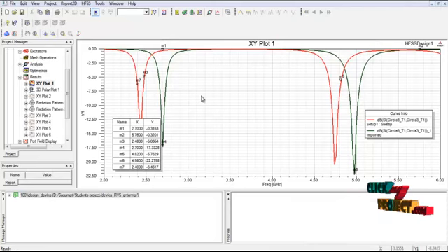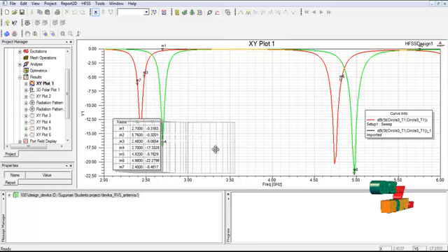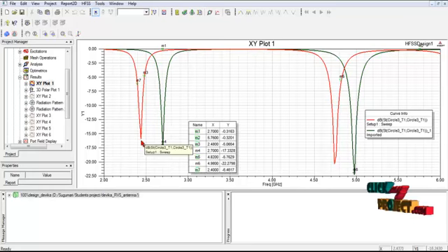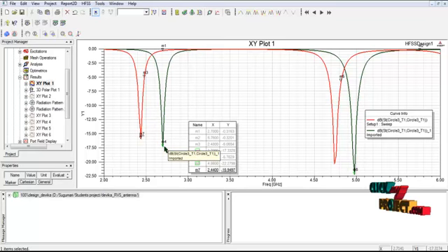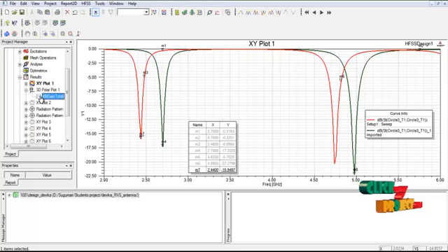yeah, this is the return loss graph. Below minus 10 dB is the working condition of the antenna. For example, this point is indicated at 2.4 GHz, minus 15 dB, and M4 is at 2.7 GHz, minus 17 dB. So like that, this is the return loss plot, and then the gain total.